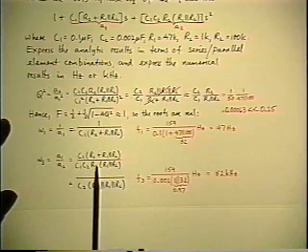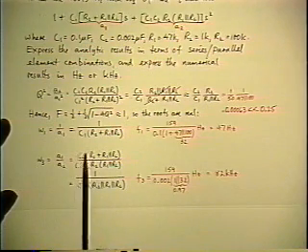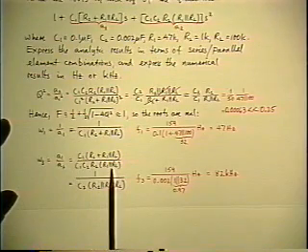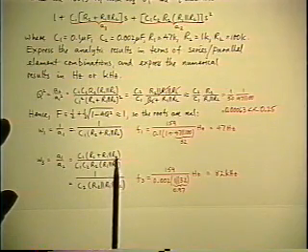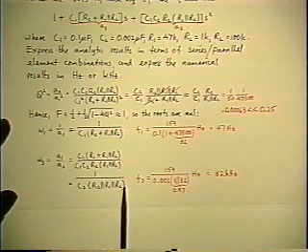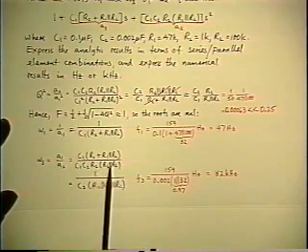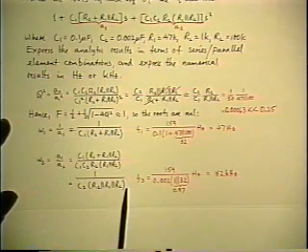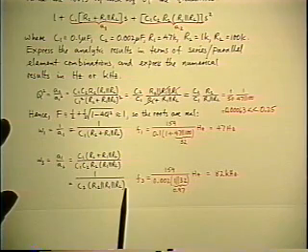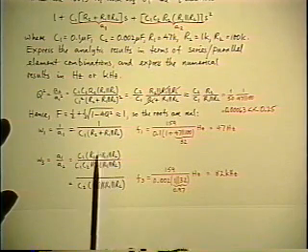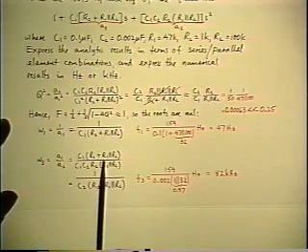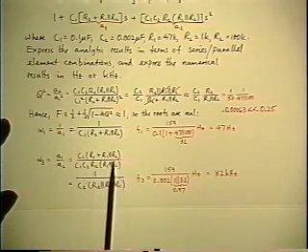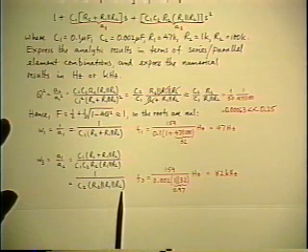The other result is immediately reducible because the C1 cancels, and you're left with sum over product, which is 1 over parallel combination, in which one of the components is already a parallel combination, so you end up with a triple parallel combination. The parallel combination is slightly more obscure in this case, but still you should practice looking for it and recognizing the result when it's there.